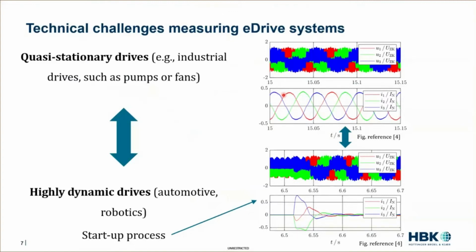And therefore, if we are interested in values such as active power, apparent power, reactive power, all power quantities, RMS values, but also fundamental quantities, then we can apply the well-known laws which are part of the standards. All of them are based on detecting the fundamental cycle of those periodic signals and then do evaluations based on this cycle.